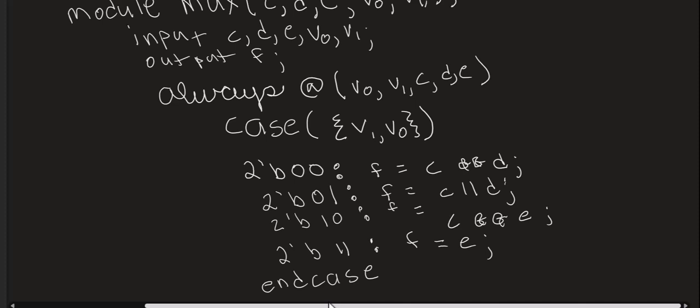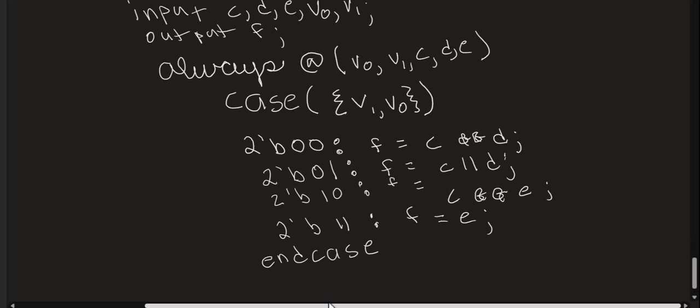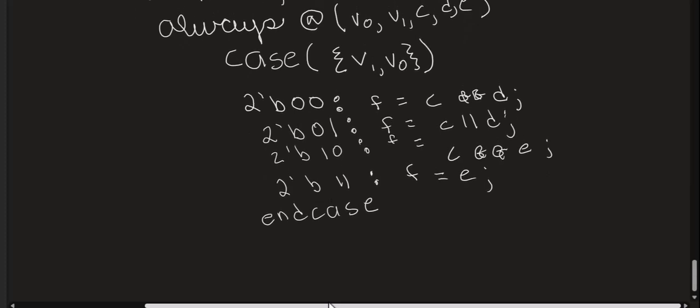I didn't have a begin on my always block, so I don't need to end the always block. And that's the end of the module, so end module.